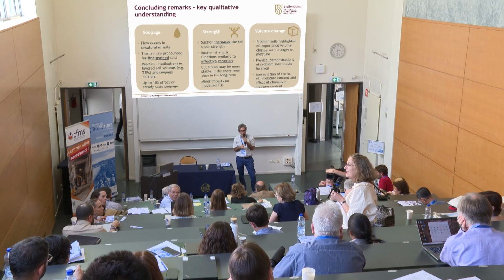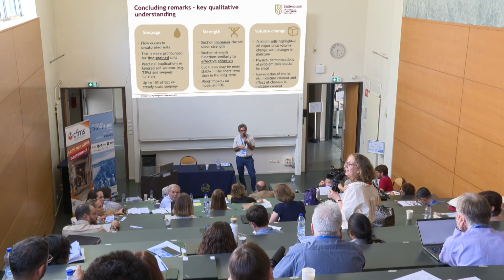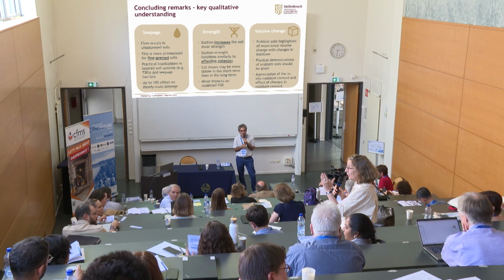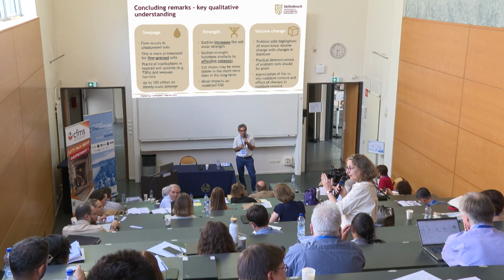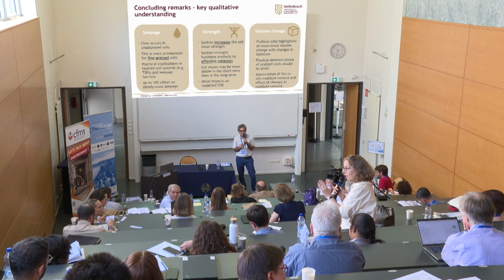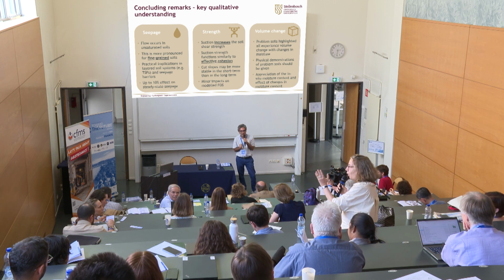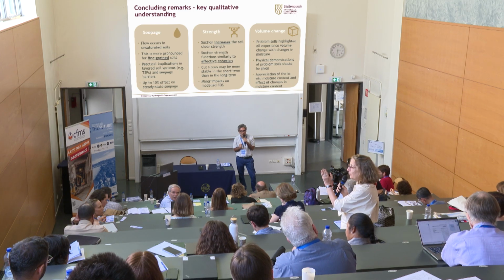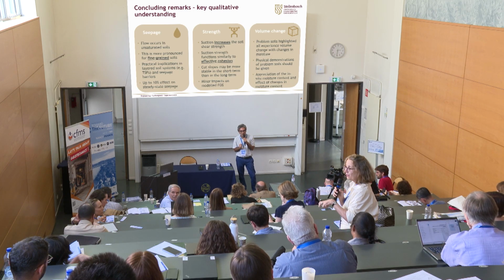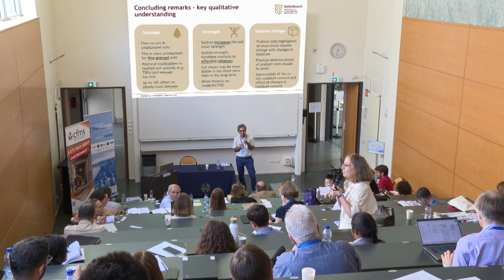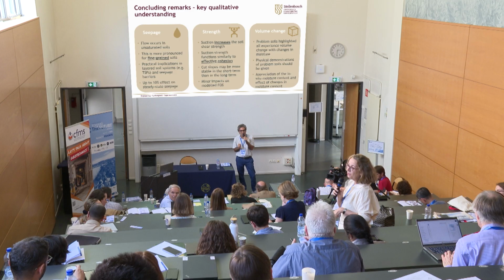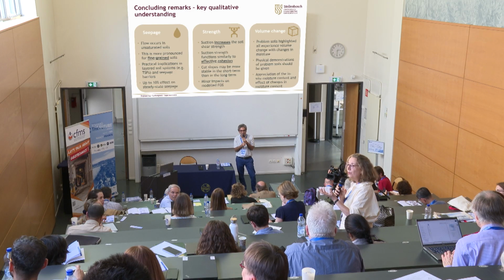Because it's much easier for me when I draw the saturation line, because I know that on the wet side of the compaction curve, I am close to the saturation. So I don't have room to reach the saturation because of the bubbles. I am not able to eliminate the bubbles when I'm doing the compaction work. Do you see? That's the reason, because you're right.